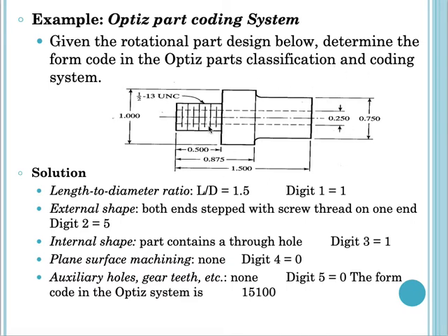This is one part where this is 1/2-13 UNC, that is unified coarse pitch threads. Half is the major diameter of this and 13 threads per inch, and this is the diameter, and here up to here is the dimension. From the job, the dimension is 1.5, and there is a hole throughout, that is 0.250, and the end dimension is 0.750. This is what is given.